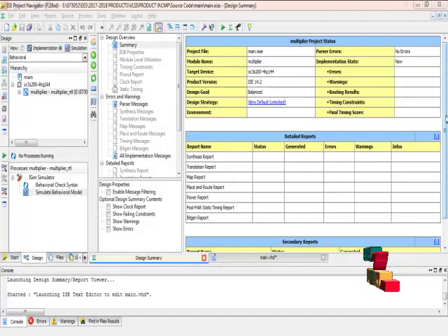Now we are going to discuss our product running procedure. In our process, the 8-bit Radix-4 Booth multiplier is implemented using the VHDL language in the Xilinx 14.2 software tool. Now the implementation and coding are completed. After that we go into the simulation part and implementation result. In the simulation process we graphically generate the binary waves to get the output, and in the implementation result we get the schematic diagram and design summary, based on which we see the improvement of the results. First we go to the simulation process.